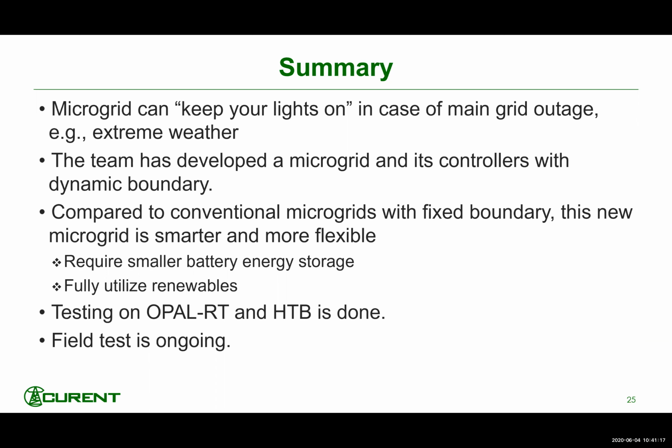Our team has developed a microgrid and its controller with dynamic boundaries. Compared with the conventional microgrid with a fixed boundary, this new microgrid is smart and more flexible. It can require a smaller battery energy storage, because battery storage is quite expensive for now. And with the flexible boundary, we are able to fully utilize the renewables.